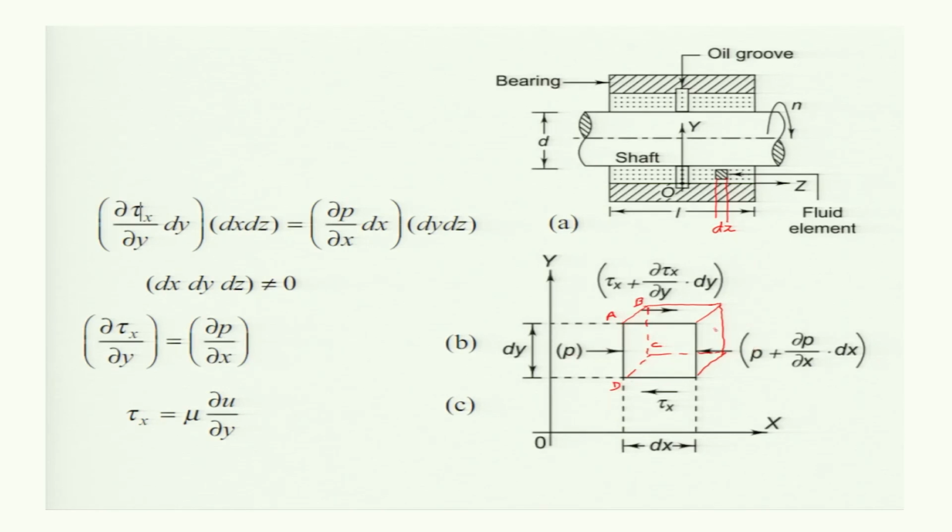Similarly, the force acting on the plane E, F, G, H will be P plus del P divided by del x multiplied by dx, multiplied by dy and dz.